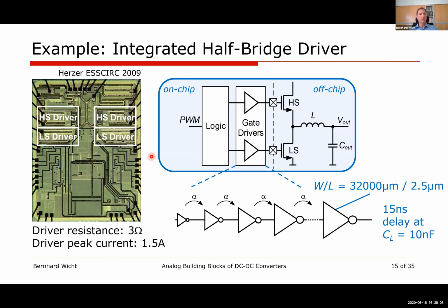And that's the reason why it covers quite a large area as indicated here. So each high side and low side driver accounts to roughly 1 square millimeter in size. So it's a square millimeter, it's really large. And so it's probably worth talking about the right optimization in terms of these stages and scaling factors.